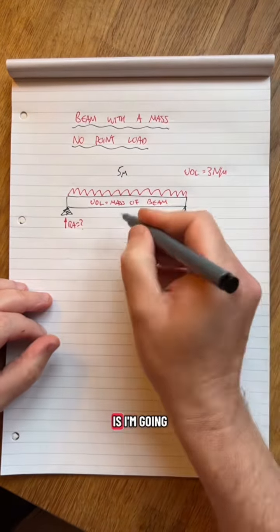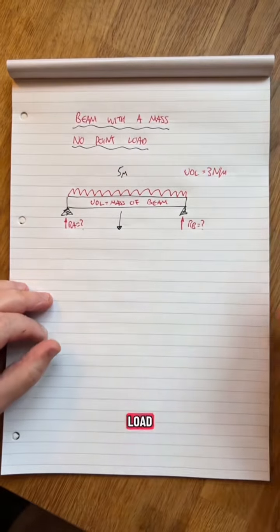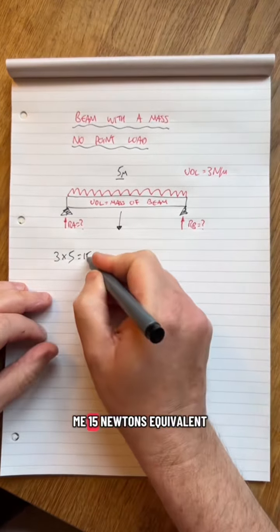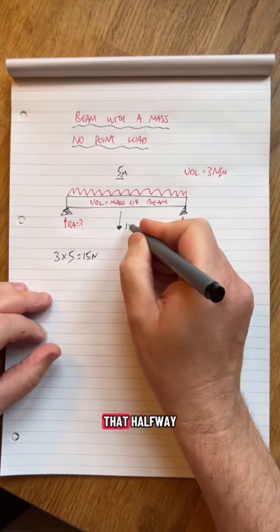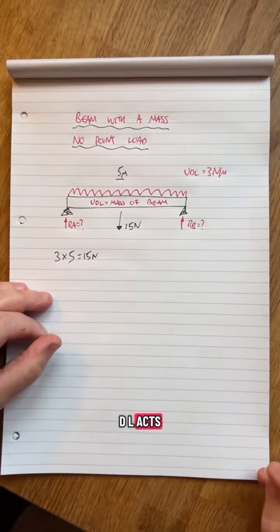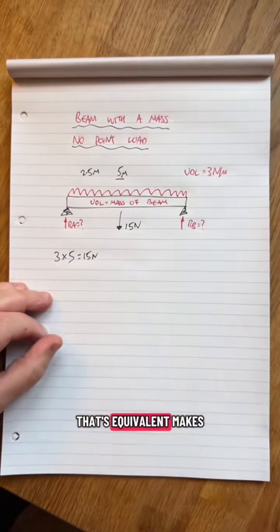The way you deal with this is, I'm going to convert the UDL to an equivalent point load. So I'm going to do 3 newtons per meter times by 5, because it's 5 meters. That gives me 15 newtons equivalent. What you do is you put that halfway, because the UDL acts across the entire length of the beam. So you put it halfway of where the UDL acts. 15, and it's 2.5 meters in. That's equivalent. Makes it easy for us.